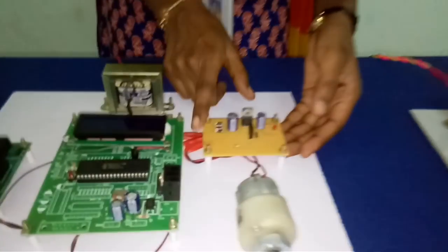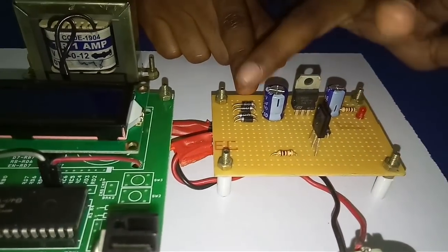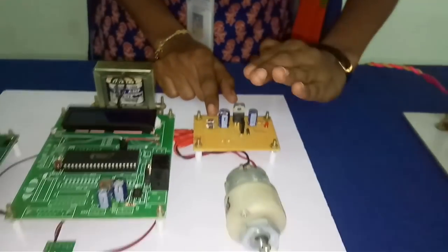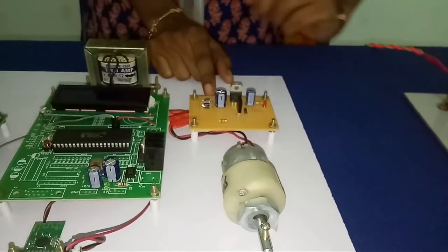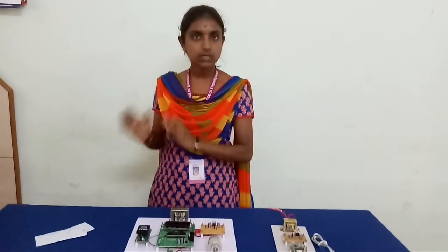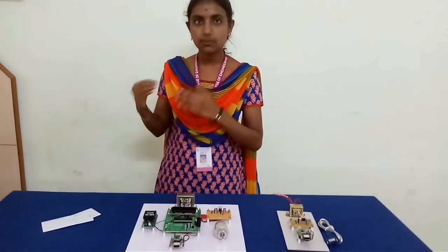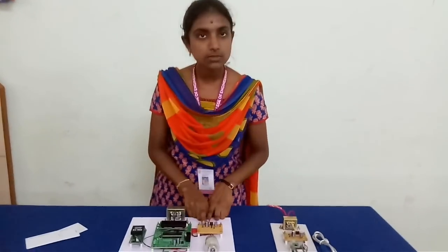It is a breadboard. It is a construction base for prototyping of electronics. It is a bridge rectifier. In our project, we have used a bridge rectifier for efficiency, and to make this process very fast. Usually, we use a half-wave rectifier. In a half-wave rectifier, only one half of a cycle is passed and the other is reduced or wasted. As a result, the output current or voltage will not be pure DC current. To make this process very efficient and to get pure DC current, we have used a bridge rectifier in our process.